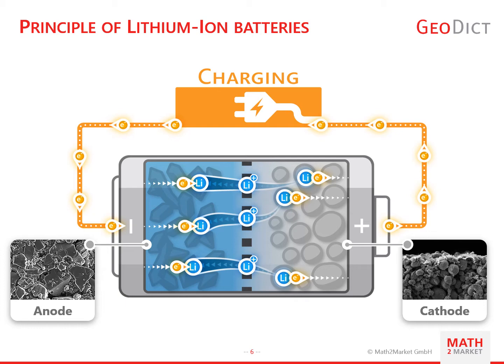At the beginning of the charging process, the cathode is full of lithium atoms and the anode is almost empty of lithium atoms. During this process, lithium atoms diffuse from the center of cathode active particles towards the interface of active material and electrolyte, the so-called Butler-Volmer interface. The lithium atoms lose an electron and travel through the electrolyte and the separator to the anode active particles. The electrons travel through the carbon black and binder to the current collector and then through the charging device to the other side. On the anode side, lithium atoms meet other electrons and they migrate into anode active particles.